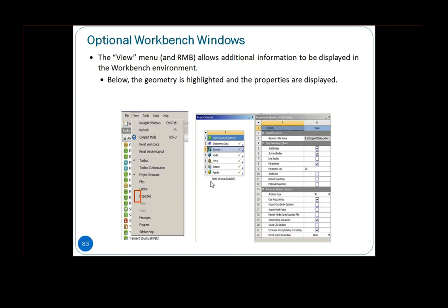Then if you look into the properties under geometry, later on I will show you under geometry, if you go to view property, there is a window that tells you what analysis you are looking into. So you tick solid bodies, surface bodies, line bodies, depending on what bodies you are actually looking into.